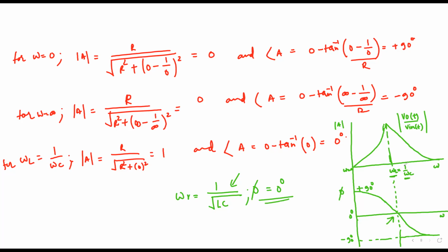So we see that we have plotted impedance versus frequency, admittance versus frequency, and the output of this circuit versus frequency, both magnitude and phase. But how do we verify it? Actually, are these values for the magnitudes and the phase matching what we have calculated? We can do that. We can actually use the SPICE circuit. Let's see right here.